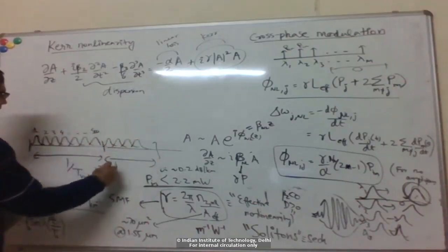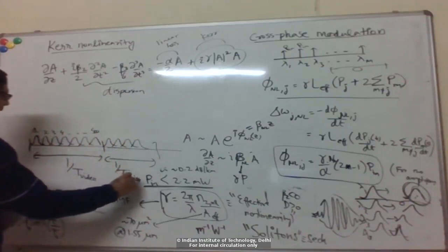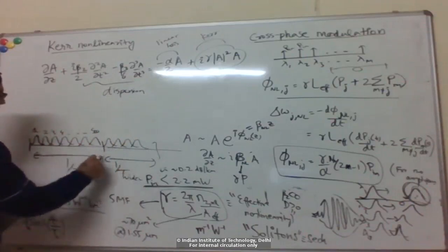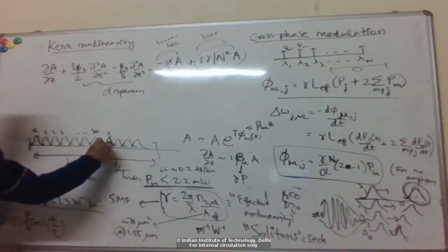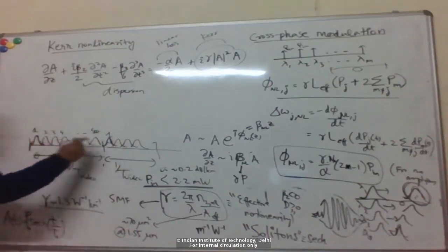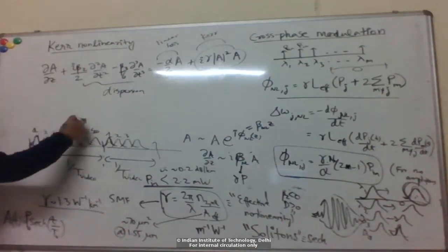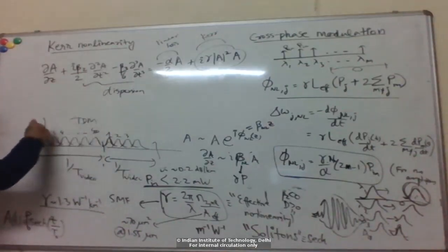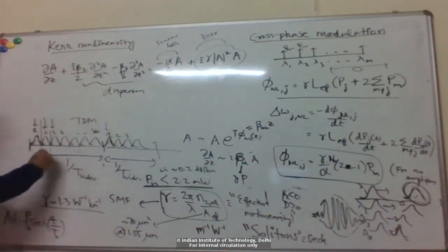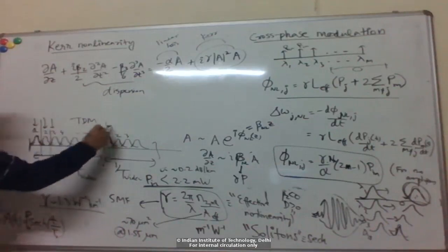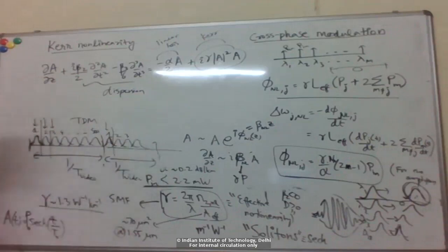And then after a bit period of 1 nanosecond, now I have the second bit of the first channel, and so on. So this is called time division multiplexing, with different time slots. The first slot is for the first video channel, the second slot is for the second video channel, and so on.